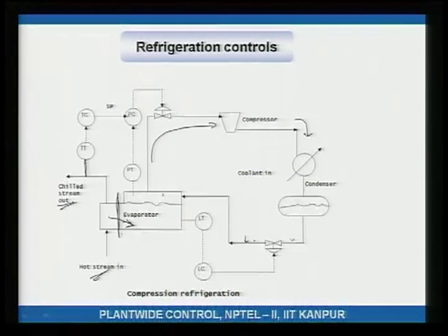And what is the pressure controller doing? Well, the arrangement here is by throttling the suction valve to the compressor, okay. So, that is how this works. So, what we are essentially adjusting is the temperature of the refrigerant, increasing it or reducing it to remove less or more heat, okay.